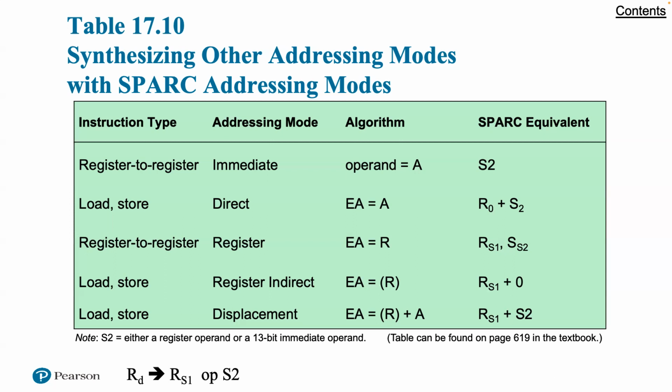Signed integers are represented in 32-bit 2's complement form. Only simple load and store instructions reference memory. There are separate load and store instructions for word, that's 32 bits, double words, half words, and bytes. For the latter two cases, there are instructions for loading these quantities as signed or unsigned numbers. Signed numbers are extended to fill the 32-bit destination register. Unsigned numbers are padded with zeros.